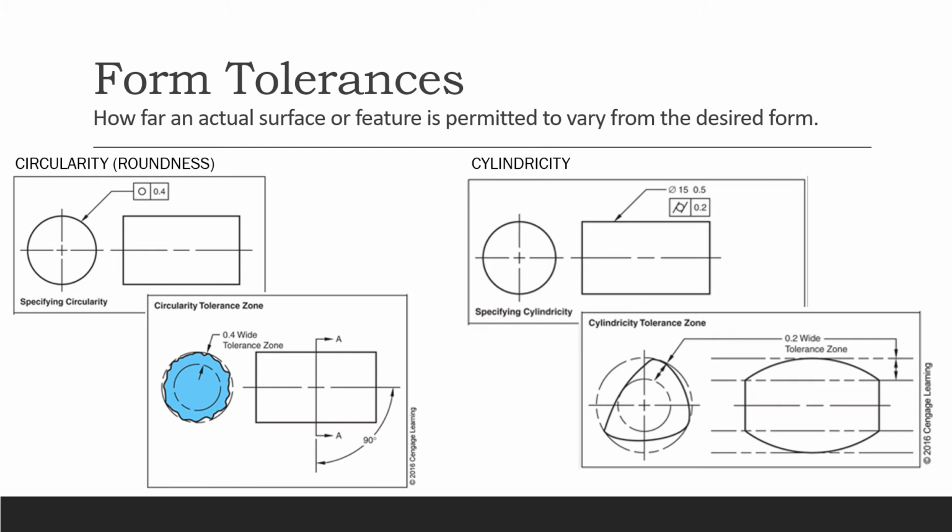So now I have a frame, and I'll take a look at the frame. You should know that it's telling you the cylindricity, and the tolerance is 0.2. That cylindricity has to be within that tolerance, which from here to here is 0.2 wide. See that little arrow showing? I also draw this for you right there. Don't pay attention to this side yet, okay? We're concentrating on this side for your course.